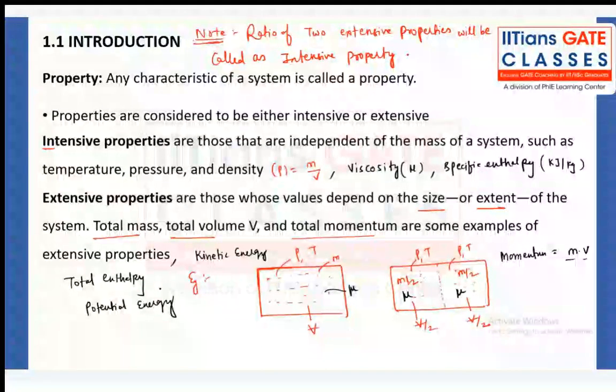See, what about the internal energy, guys? Whether it is a property or not? Yeah, it is a property. But which property? If you know a little bit about thermodynamics, then definitely you can answer, guys. Internal energy is an extensive property. But if you write the specific internal energy, that will become an intensive property. Getting my point?